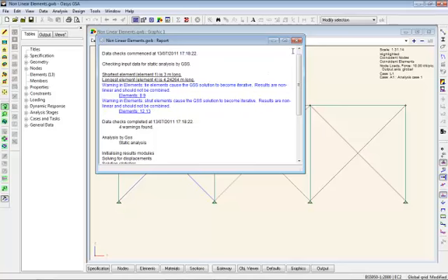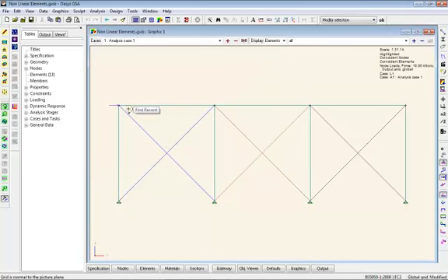What this means is that when you apply this load, this tie here will go into compression. GSA will say it's a tie, can't be compression. It will switch it off and then rerun the analysis. Now sometimes you might find it can oscillate between two conditions, in which case it's worthwhile adding in a normal or horizontal load.